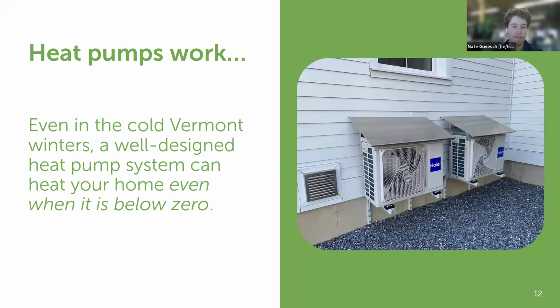It's important to remember that these systems need good design and good sizing. And there's also an element for existing homes where it's a really good idea, and in fact essential in most cases, to also improve the thermal envelope of the home, or the insulation and air sealing in the home. So we can talk a little bit about that as we go along, but I just really want to reemphasize this point that heat pumps do work as long as the system's well designed and your home is set up for it. Some of the stories you read online, I follow a lot of industry news, and you read some horror stories, and when you dig into the details, you see mistakes that were made. And when people make smart decisions, by and large, we get really positive feedback on heat pumps working at really cold temperatures, even up here in Vermont.